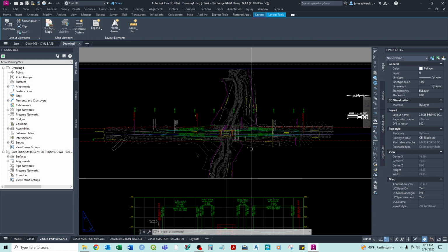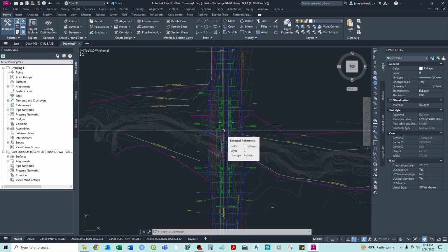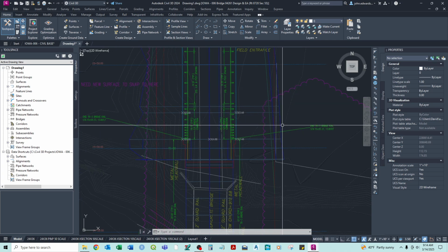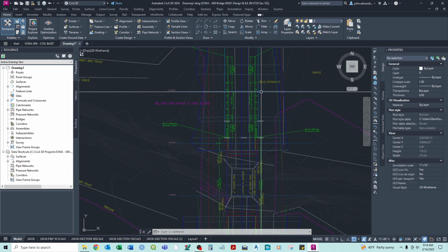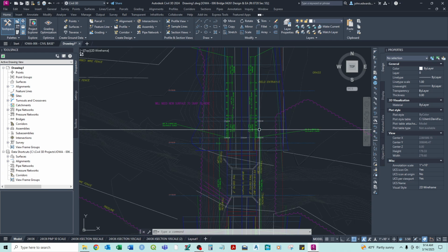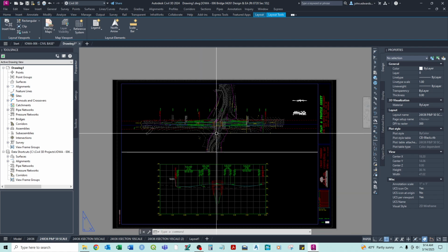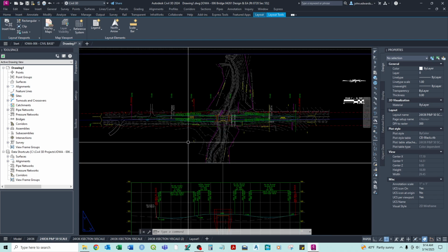Speaking of labels, you can add labels at any time in model space. We can add these in as we go, but it's trickier to work with them because potentially the orientation is not the same as in our sheet. The annotation scale is not the same. So I generally prefer to do labeling using the viewport itself, because it's locked in a set scale, a set orientation, and everything will come from that.